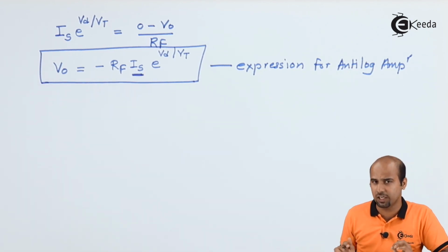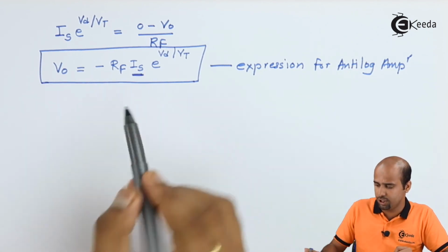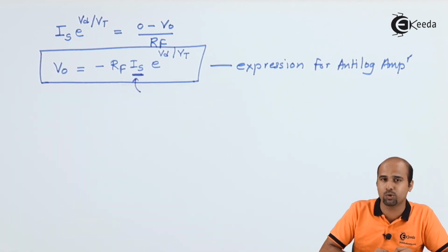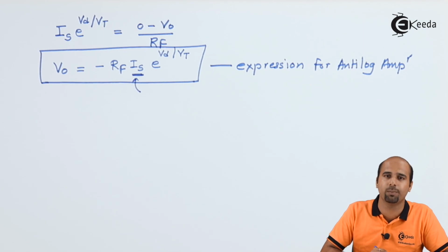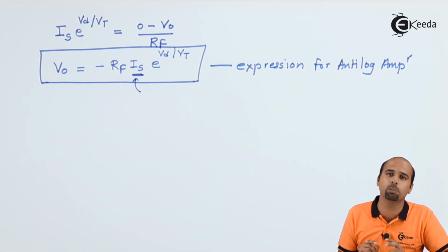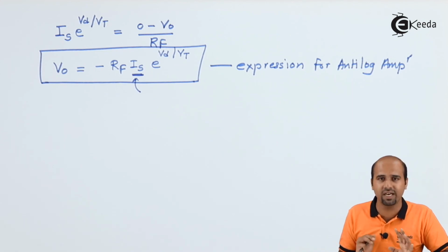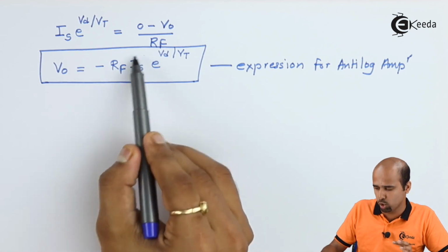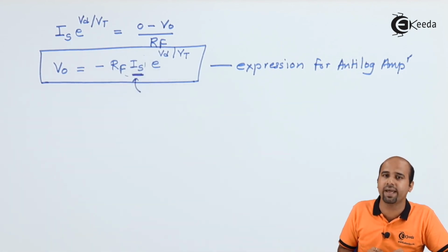We can easily solve this particular issue of temperature dependency by using 4 operational amplifiers. One is with V1, one is with VREF, one is the differential amplifier, and another is the buffer circuit, such that we are getting exactly the same expression but excluding the parameter Is, which is dependent on the temperature.